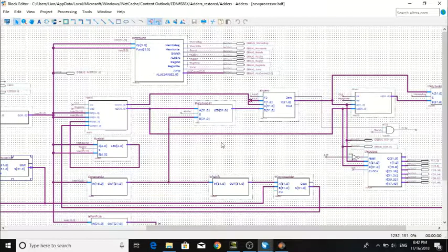As jump does not require any registers, ALU calculation or memory, no other components are required to be active. Thus, only the jump signal here is set on high, whereas the others like ALU control, register write, memory write are all set to low.